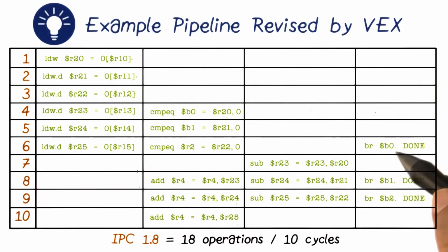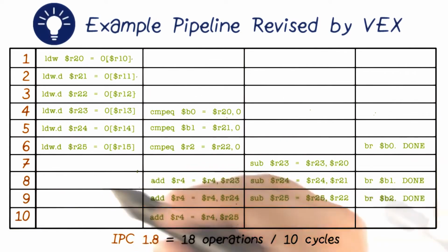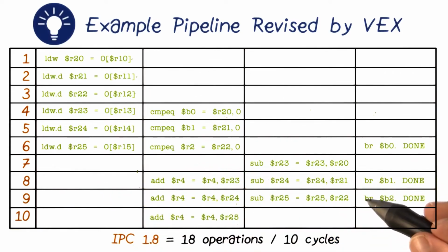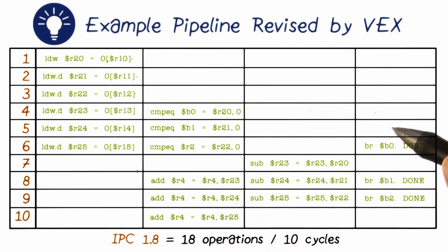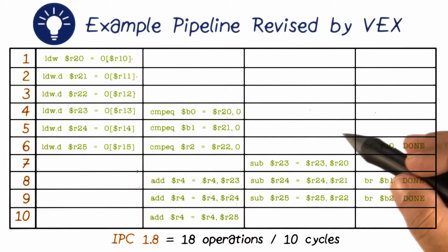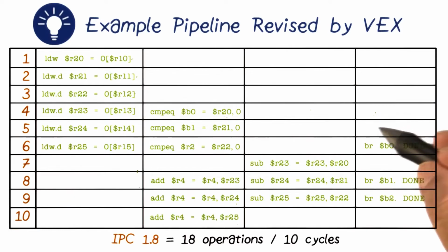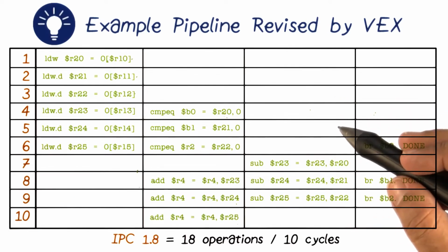In fact, the maximum number of instructions that we are able to place in a given slot is just 3, not 4. And that's why the width of the VLIW architecture, that is, how many instructions could go in parallel in a given slot, is carefully decided. It should not be too small because then we'll have more untapped parallelism, and it should not be too wide because then there will be a lot of empty slots left out, for which we are paying the price of energy.